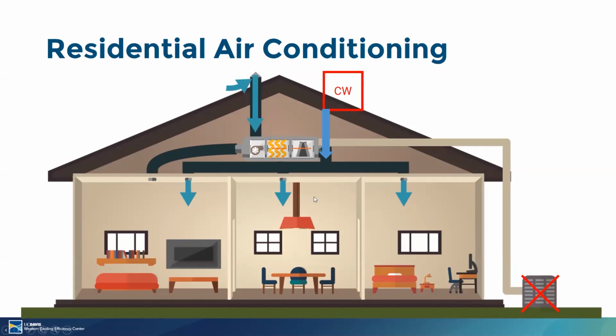So then I had to hack up this drawing here because I didn't have time to ask Paul to draw me a new one. But I just wanted to say, okay, how would we switch out a compressor-based air conditioner for a Climate Wizard? And I show it here sitting on the roof. It wouldn't necessarily have to be on the roof, but it made my drawing easier. So basically you have this indirect evaporative cooler using outside air, and then it's supplying a portion of that air to the building. In this particular case, this system is designed not to use any return air.